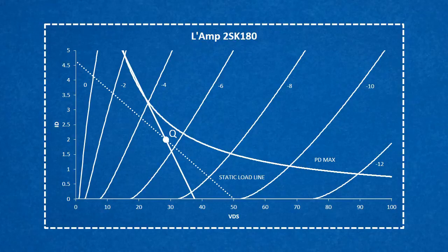Alternatively, if our goal is minimal distortion at low power, the Q point might end up somewhere else on the static load line. This is our approach, where we are prepared, if necessary, to trade a little bit of output power or clipping symmetry for really good performance at a watt or less. And we can certainly aim for both by tweaking the operating point and load.